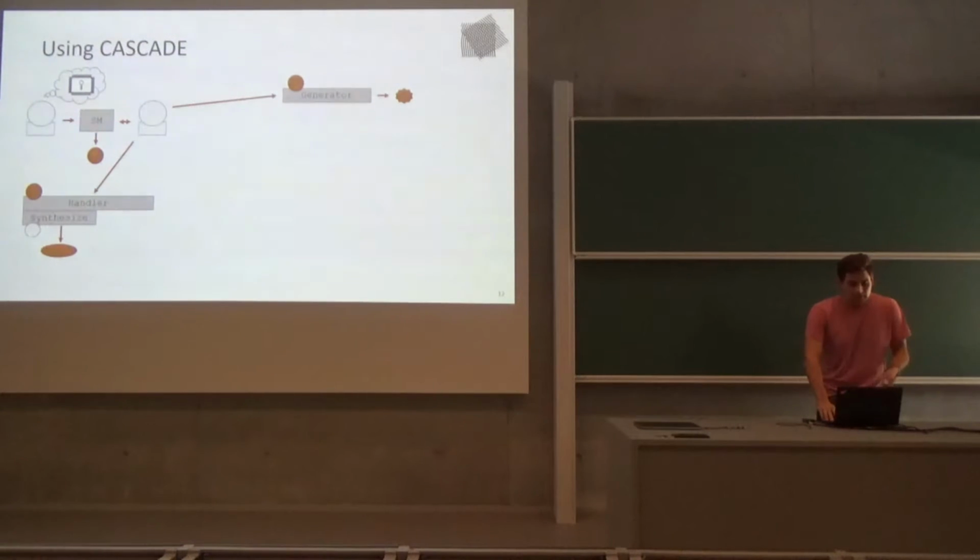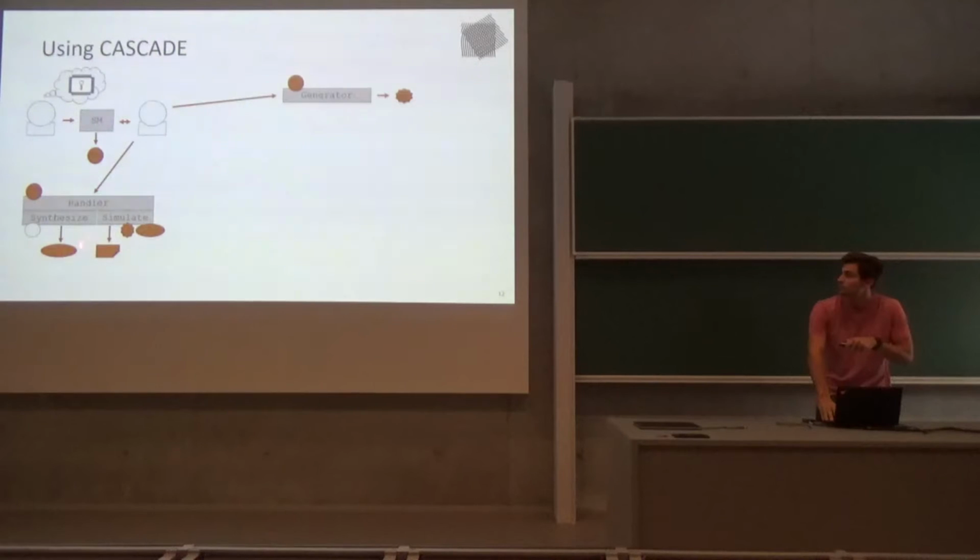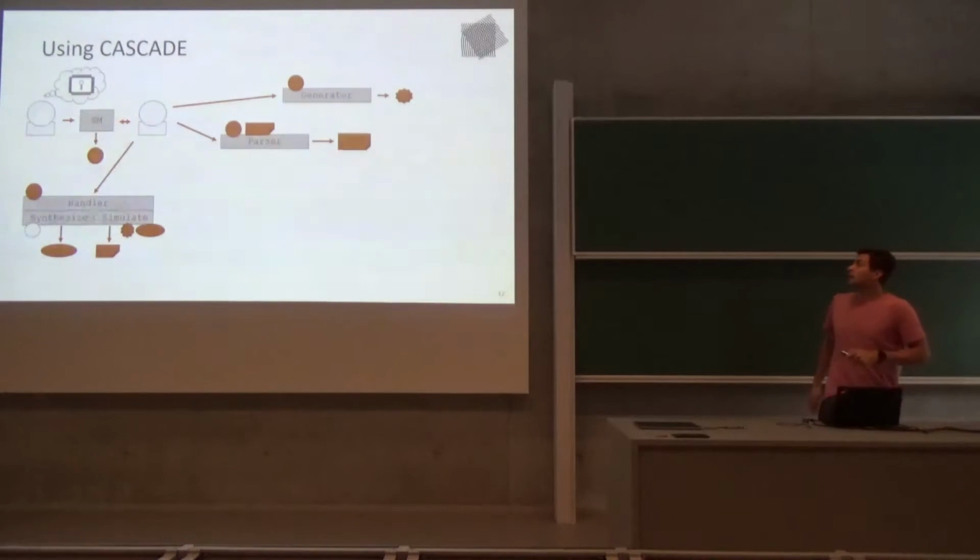So you would synthesize and create something like a new stage, a gate-level netlist or power netlist or whatever. Then you would also want to simulate them using one of the simulators from the framework. These simulators again rely on the automatically generated data and the typical netlist that you start with to generate an output. Once you have this output of a simulator, you start parsing it using one of our parsers, which are written in C, optimized, etc.